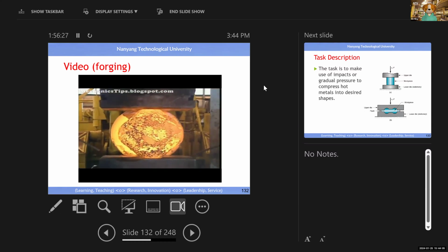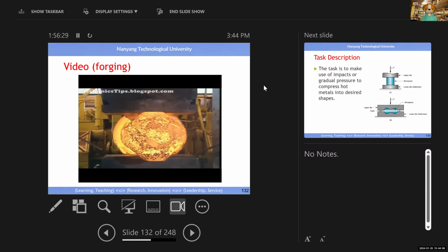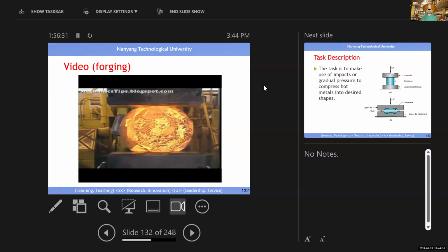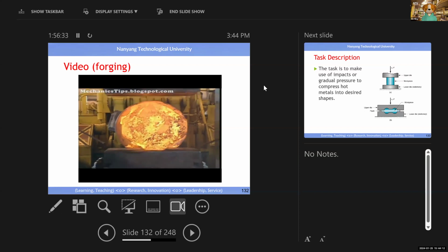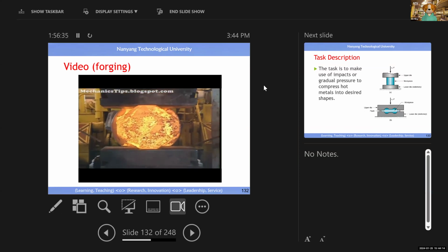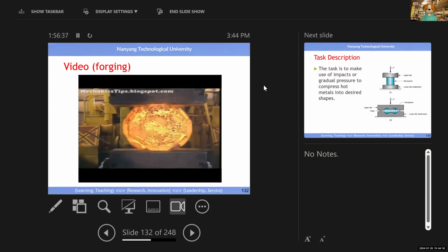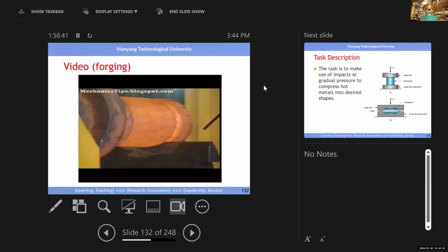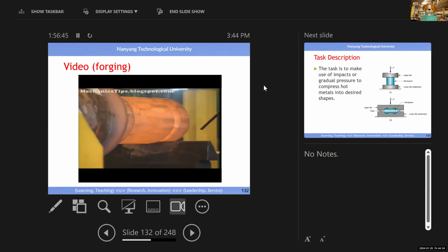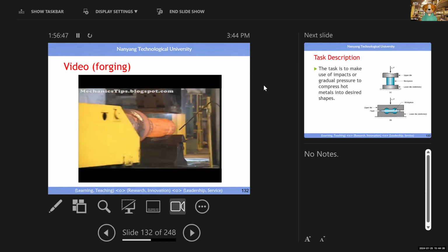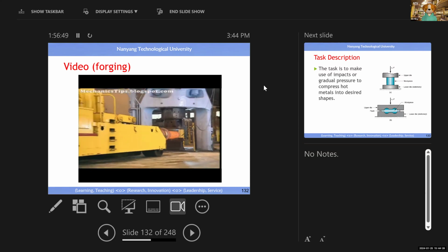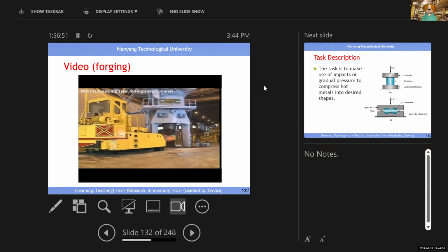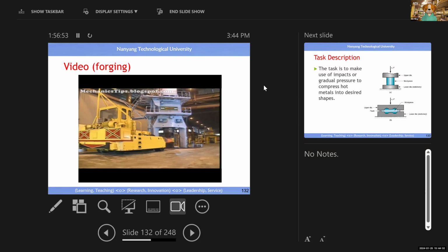Lengthening and upsetting are typically done using forging steps as the workpiece is incrementally advanced lengthwise and rotated on its longitudinal axis. There is essentially no limit to the size of forgings that can be made using open die forging. They can range from a few centimeters to 30 meters in length and weigh from a few to up to several 100,000 kilograms.